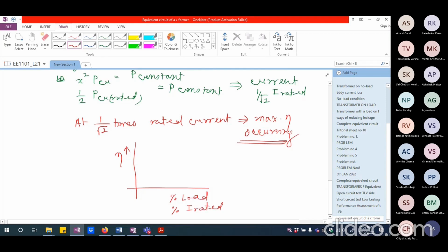Hardly ever will we have any variation in the voltage. Any generating station normally generates only around 15 kilovolts or 12 kilovolts. That is the rated voltage. Then it will be stepped up to 465 kV or 800 kV before it is transmitted. So all those things are set in stone. That cannot change. So the transformer will always be applied with rated voltage and rated frequency.